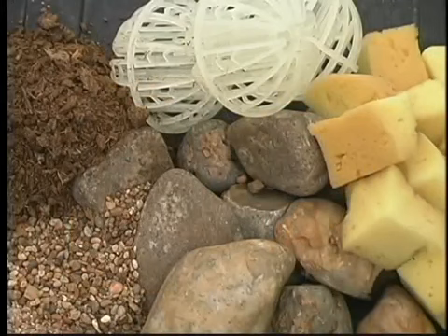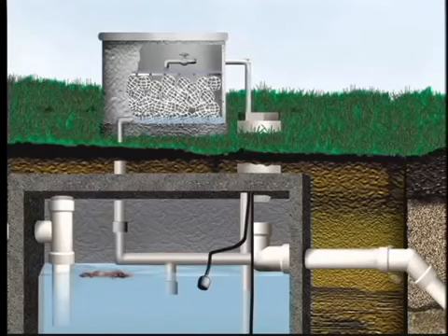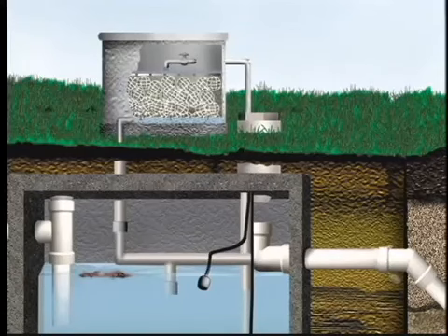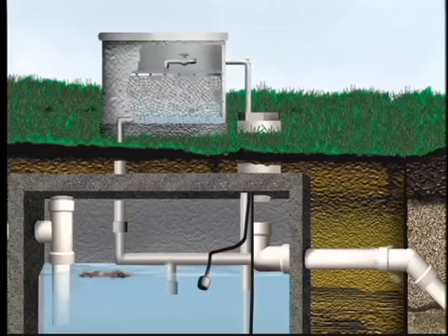The main difference among these filters is the size of the media and the amount of wastewater that can be treated by the media. Media filters are used to aerobically treat the wastewater with microbes growing on the media surface. These filters remove large material, absorb small and dissolved material onto the surface of the media, and this waste material is decomposed by the microbes. Media filters reduce the quantity of organic matter, solids, nutrients, and pathogens. The quality of the effluent depends on the media size and how the water moves through the system.